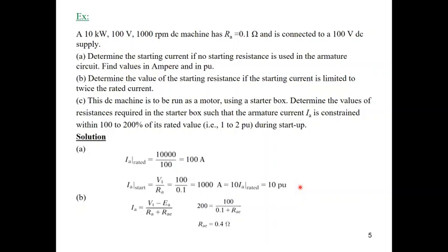So if the machine is a high power machine, which means the inertia of the machine is high, it will take some time to start up, maybe hundreds of milliseconds, or maybe around 0.9 or 1 second. However, if the machine is very small power or very small size, with small inertia, it means the machine can start in several milliseconds. So based on that, the value of current will vary.